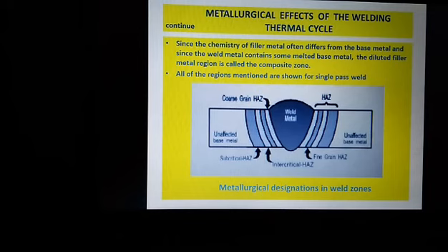Since the chemistry of the filler metal is often different from the base metal, and since the weld metal contains some melted base metal, the diluted filler metal region is called the composite zone. All of the regions mentioned here are shown in the single pass weld.